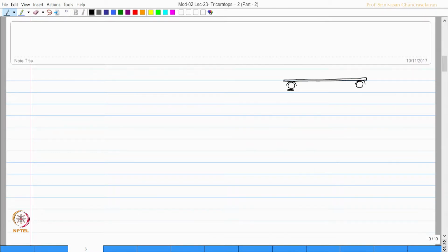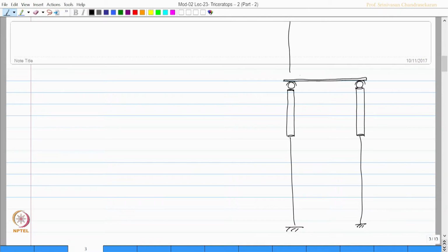which is now connected to the buoyant legs, which are anchored to the seabed using high initial tension tethers, similar to that of a tension leg platform. Being a triangular geometry, the CG will be shifted towards the left side. Let us draw this line as my CG line.